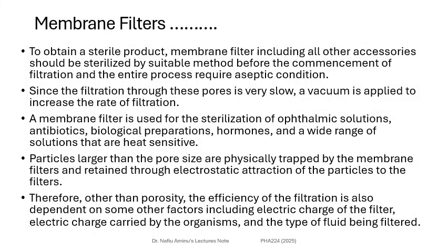So first of all, the filter medium, the container that is going to be utilized to retain the process solution, the panel and all other associated gadgets have to be in sterile form before commencement of the procedure. And the entire process has to be done in a sterile environment under aseptic condition. Since the filtration through this flow is very slow, vacuum is applied to increase the rate of filtration.